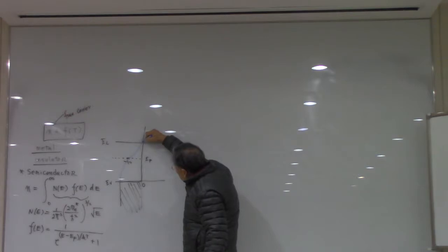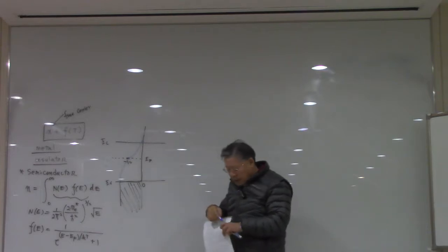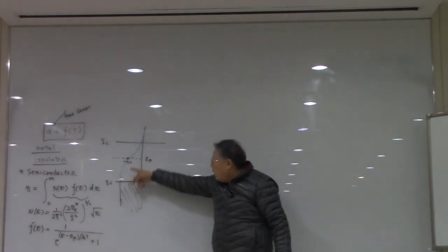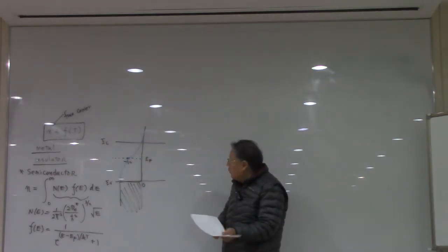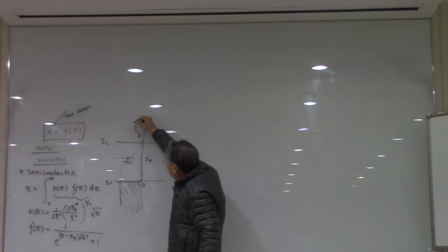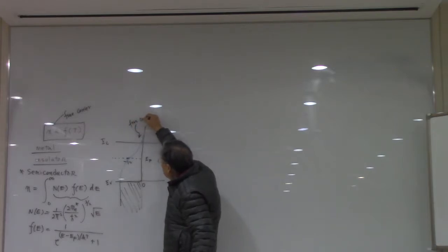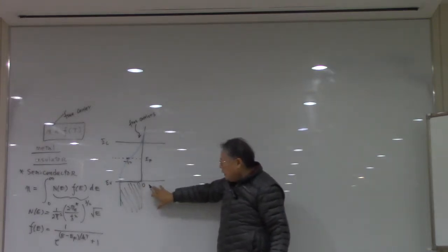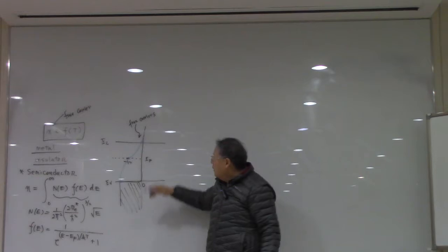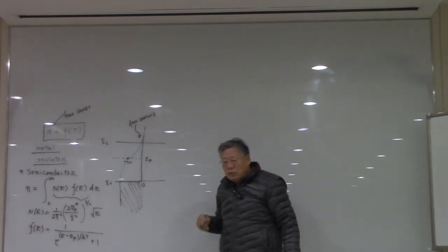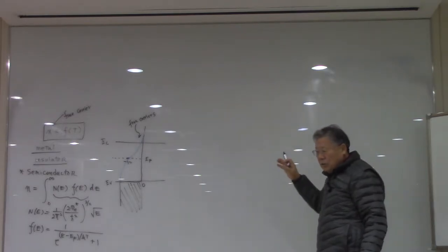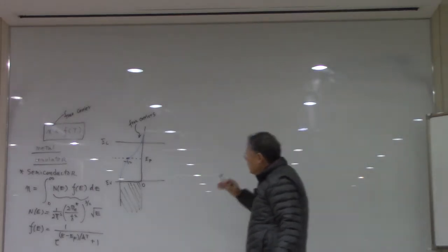So these electrons occupying these energy levels above the conduction band edge, according to this Fermi-Dirac statistics, this is the one which can be called free carriers. We are not going to talk about any electrons in the valence band. These are the electrons which can move freely, so that is the one contributing to the conductivity of the material.